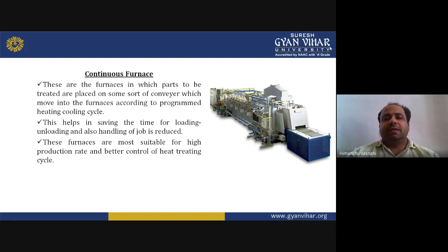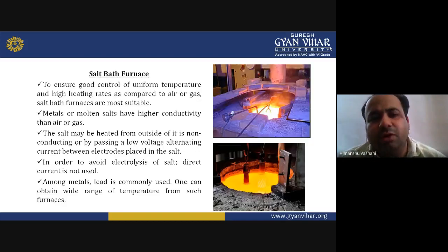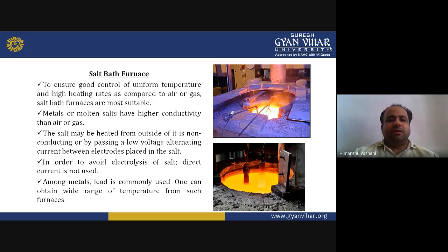Okay. Then the salt bath furnace. Salt bath furnace is very good when you want to ensure good control of uniform temperature, and high heating rates as compared to air or gas. The salt bath furnaces are most suitable. When you need high heating rates as compared to air or gas, then you can go for a salt bath furnace. As the name says, salt bath.